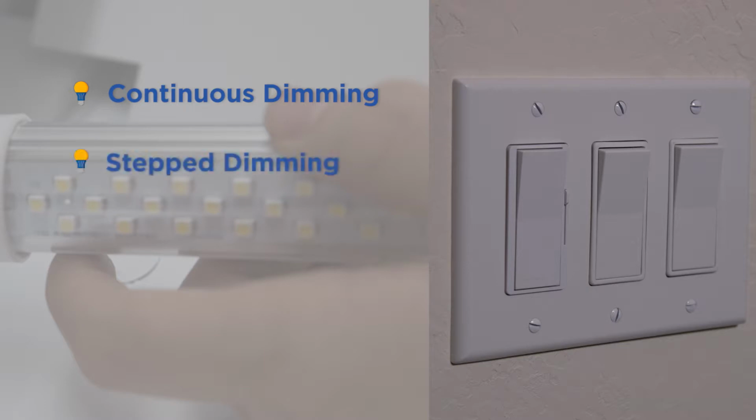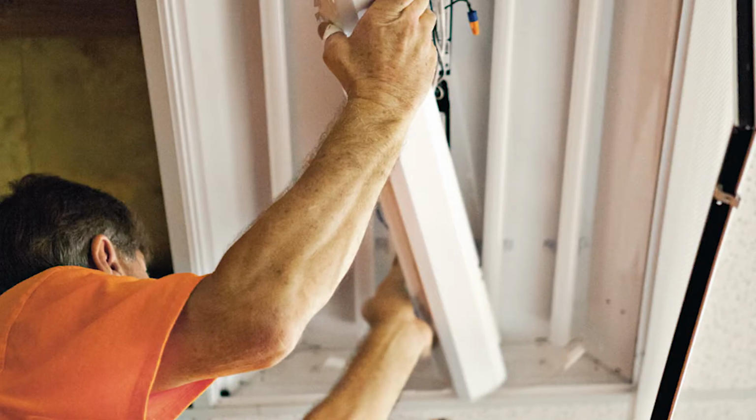Stepped dimming, for each luminaire, a manual dimming control provides at least 1 control step within the ranges specified in Table 130.1-A. For linear fluorescent luminaires with 4 lamps or more, switching alternate lamps in each luminaire. Lamps may be tandem wired such that power to each of the 4 lamps can be controlled separately by the dimming control. Multi-level lighting controls can save significant energy by providing the capability to precisely control the amount of light in the space based on occupant needs.